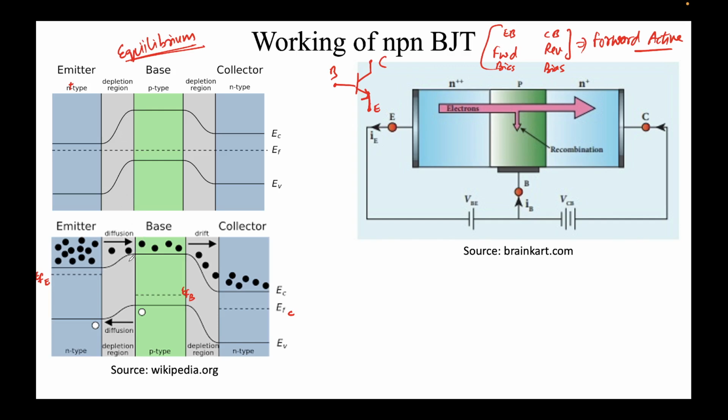What this means is that it's a forward bias. Only in forward bias the band bending reduces. This is, let's say, VBI. Here it's not that, it's VBI minus VBE, the applied potential. VBE is the potential that we have applied.